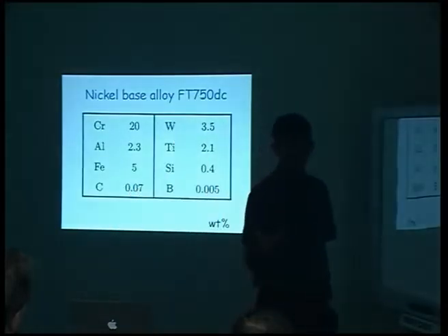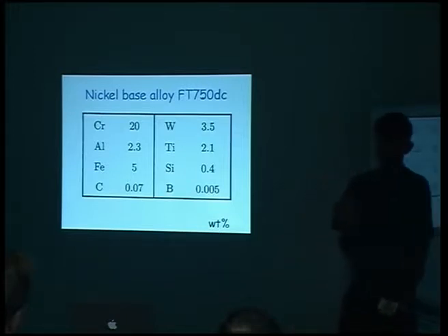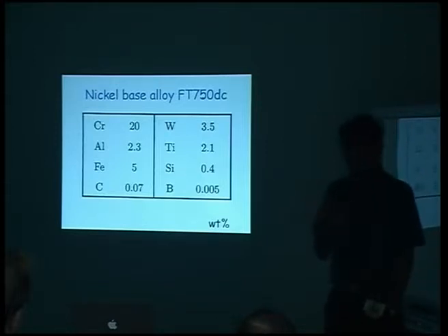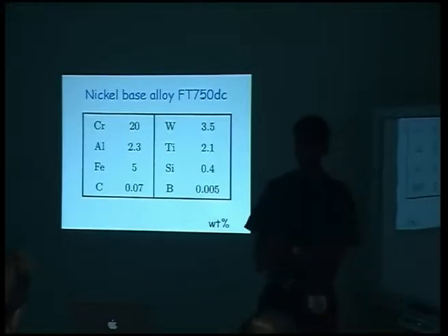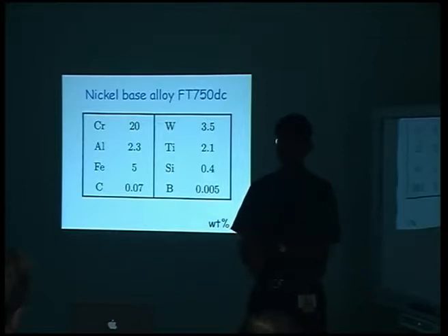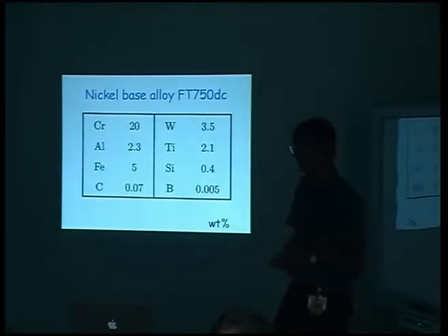Now, steels, people have tried extremely hard, ferritic steels, to get them to operate at a temperature of 650 degrees centigrade. Even we might succeed in doing that. 650 degrees centigrade for 25 years with a stress of 100 megapascals. Right now, the best we can do is 620 degrees centigrade, but there are huge research programs to go to 650 degrees, because ferritic steels are absolutely wonderful. They have a low thermal expansion coefficient, high thermal conductivity. So, when you get temperature fluctuations, you don't get thermal fatigue, etc. Whereas austenitic steels have the opposite, and they fracture very quickly in the power station scenario.